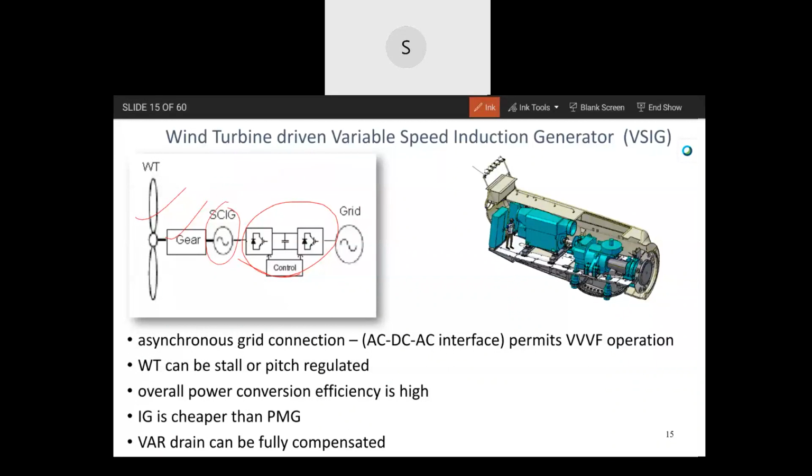Environmentalists are against mining of rare earth for making permanent magnets. So that should be limited. We should not use it in each and every case, only when it is essential. EV solutions can be made with an induction motor. Anyway, in wind, of course, it helped. And in the beginning, in '98, when it came, people were skeptical because prior to that, permanent magnet had a life of 4 to 5 years.